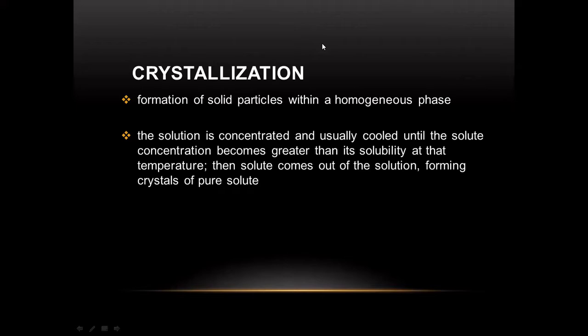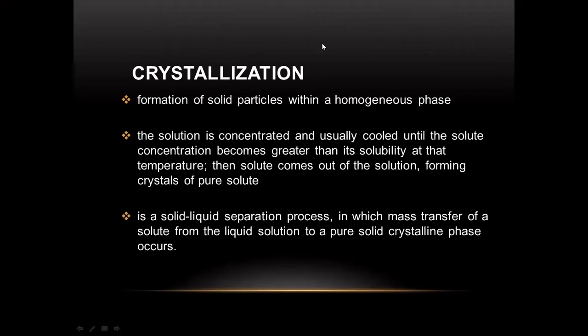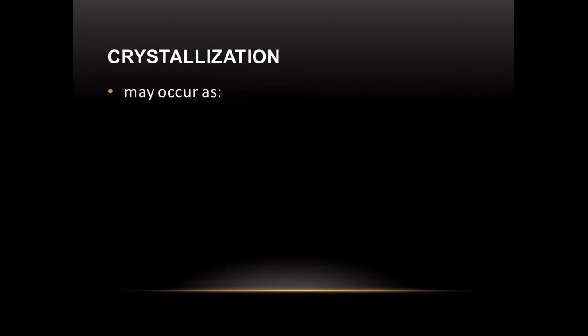Now, it could be a simple case of cooling, or it could be a case of evaporative cooling. We can also view crystallization as a solid-liquid separation process in which there is mass transfer of the solute from the liquid solution to a pure solid crystalline phase. And that's the process of crystallization. So this is mass transfer from the liquid phase to the solid phase.